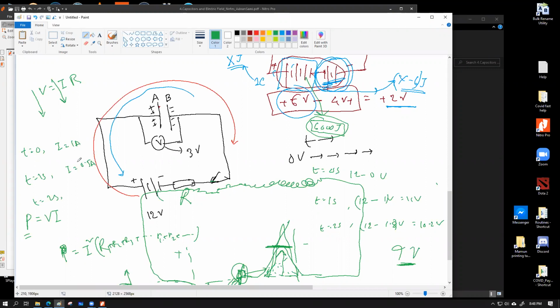I'm just doing a mathematical average to make sense of it. It's not going to be exactly a mathematical average, but just to make sense to you. If I take that for this duration, the average current was 0.75 ampere. The capacitor did gain some voltage, but once the capacitor gains some voltage, it works as a reverse voltage and reduces the available current. As a result, after 2 seconds, the current will not be reduced to 0.